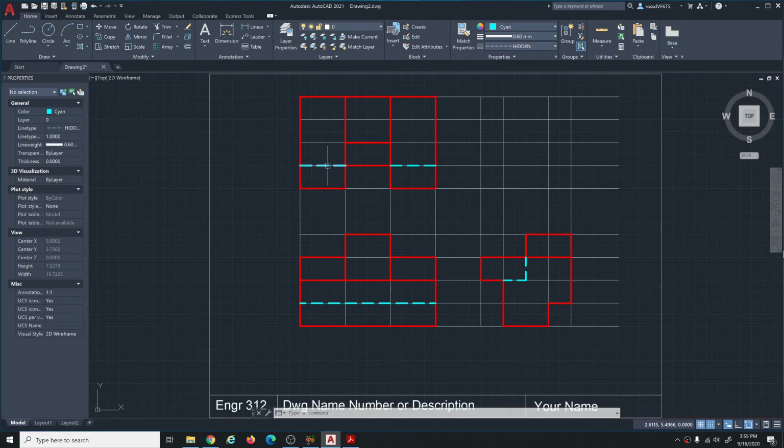And I'm pretty sure this is, oh no, I'm missing a line up here, right? This line here is the way that this corner here in the end view shows up as a hidden line on the top view. And I think that's it.